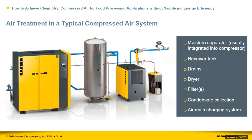This graphic shows the air treatment included in a typical compressed air system. We will go through each part in more detail, but there's one thing I want to point out before we go. There are no bypasses on any critical air quality systems. For 24/7 operations and for backup systems, we highly recommend parallel clean air treatment paths.